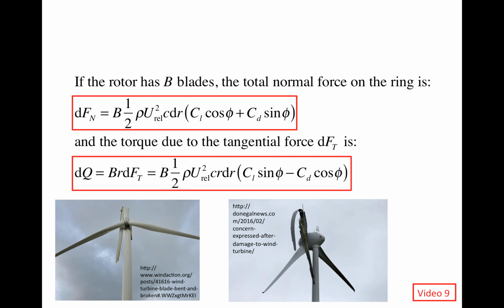So a straightforward approach to equalize the amount of loads along the blade is to reduce the chord length with radius. Because the cross sections of the blades are actually airfoils, reducing the chord length of the airfoils with radius is the same as reducing the width of the blades with radius. And that is why the blades are tapered. It's wider close to the root and narrower close to the tip.